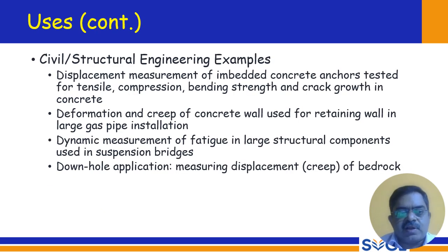In civil structural engineering, we can see displacement measurement of embedded concrete anchors tested for tensile, compression, bending strength, and crack growth in concrete. Deformation and creep of concrete wall used for retaining wall in large gas pipe installation. Dynamic measurement of fatigue in large structural components used in suspension bridges.